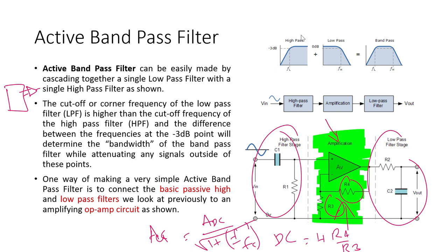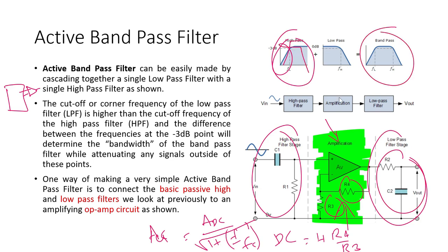So after having a high pass filter, we pass it through this amplifier to make this thing steeper, to make it go like this, and after that we pass it through a low pass filter. The low pass filter will cut some range from it, so it will make things like this. So this is our high pass filter, this is our low pass filter, and this is our filtered output signal. The high pass signal is high, and the low pass signal is already amplified, so this is high. So we make this thing go up, and this is already up, and we only need an amplifier. After the second stage, we do not need any amplifier in here. Why do we not need it? Because it is already amplified.